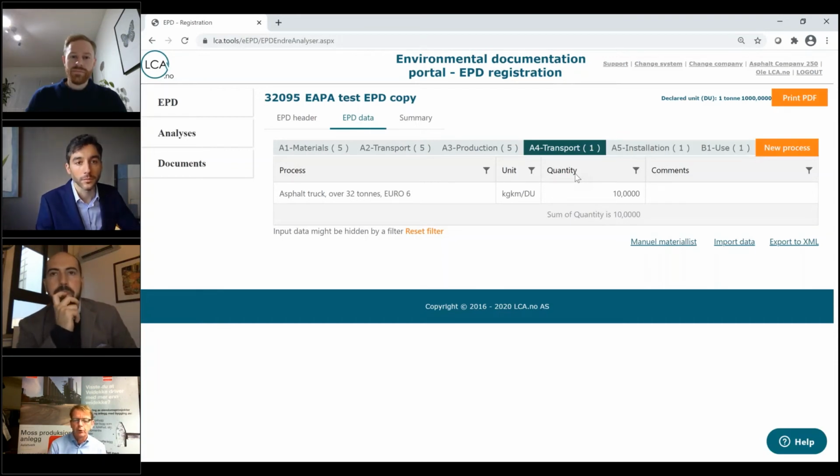So above 20,000 vehicles a day, it's 4 or 5 years normal service life, and for 3,000 annual daily traffic, it's 10 or 11 years. So we use that scenario if we have to calculate the service life.